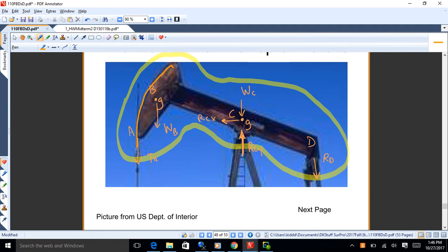Now, the other thing is, it's a good idea to show the boundary. So how that cable's modeled depends on where you cut through it. If I cut through it down where I'm showing, it would just be straight down. But if I were to cut through it up here, it wouldn't. It'd be angled. So you have to pay attention to exactly where you're deciding to cut it. Even if you don't draw a boundary, it's worthwhile to imagine that, if nothing else.